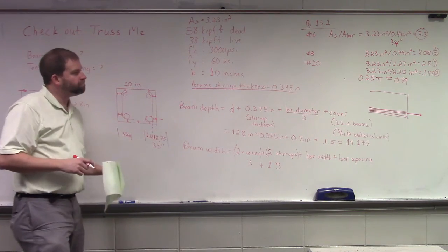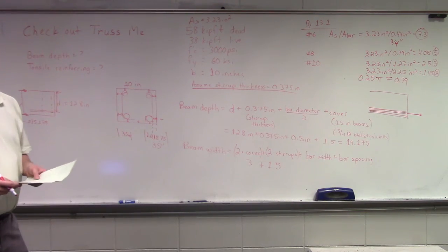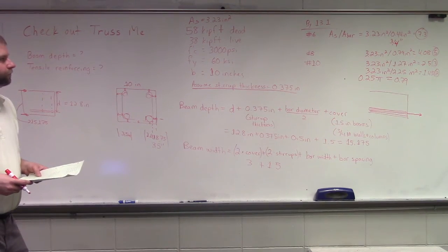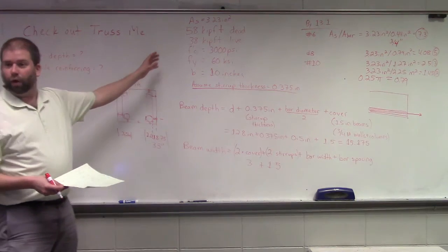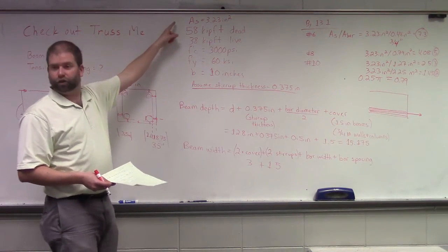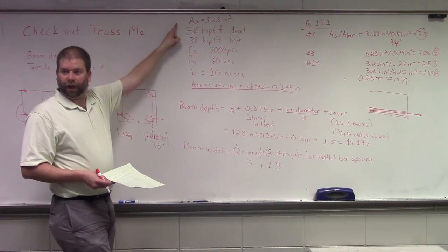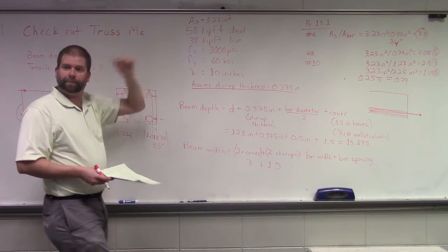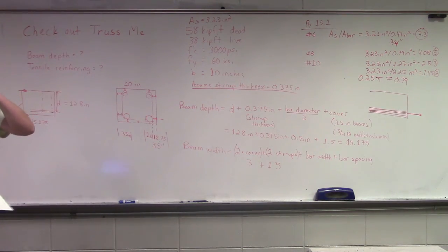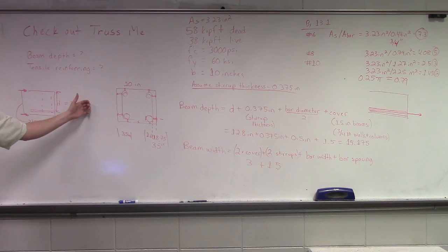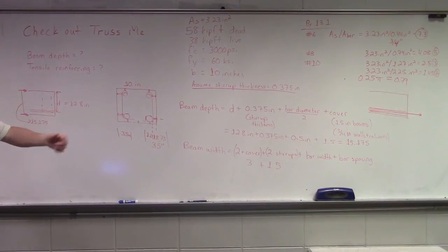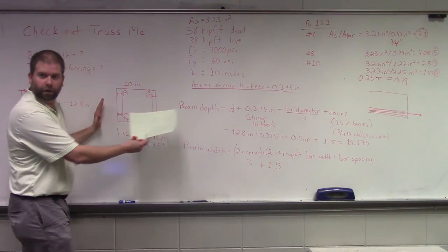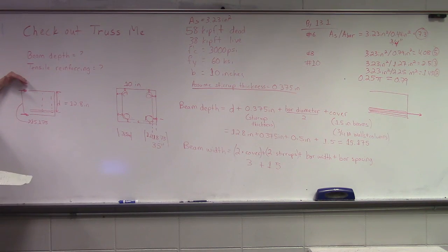So would we take that information we got for bar 14 and see if it meets up with your f'c or fy or anything? Well, we know that it will, because we determined As off of that. So from there, we can just say, you know what, they won't build it this way, it's no good. Correct. So for this particular project, this gets rejected and they say, okay, you have to reiterate this. Either you need a wider beam or you need a deeper beam, okay? Okay.